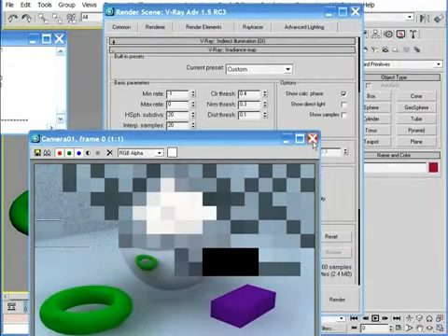So to summarize, with each successive pass, VRay determines if the GI in each area of the rendered view has been adequately approximated by the samples taken in the previous pass. If so, then no further samples will be taken, and if not, more samples will be taken on successive passes. So with each successive pass, the resolution of the Radiance map is actually doubled, and therefore VRay can potentially take 4 times the number of samples as the previous pass.